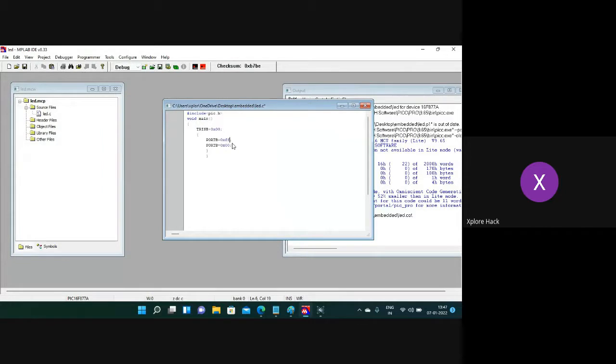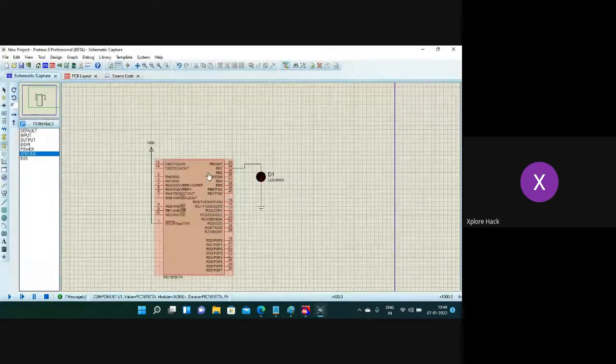So you can use all the 8 pins of this port with the help of this hexadecimal value. Okay, so this is how you'll create this program. After this, if you want to connect any input-based devices, then you have to, as I told you before, give 1 in this place. And consider we are going to connect a button within this